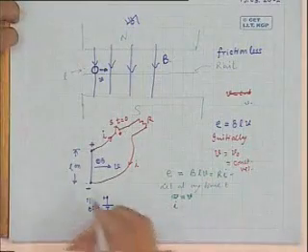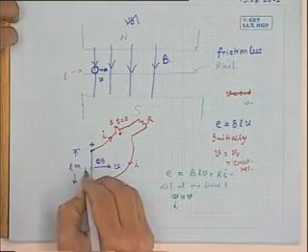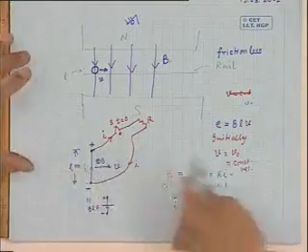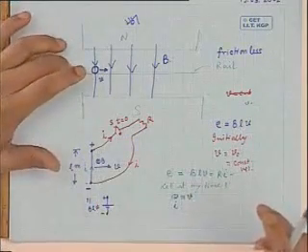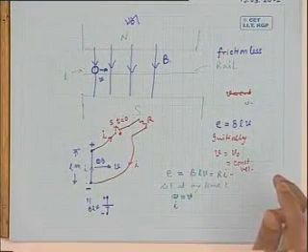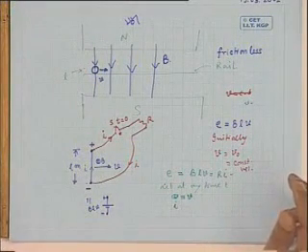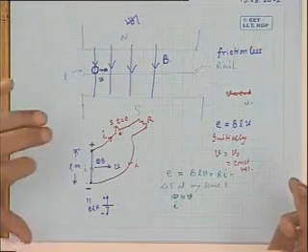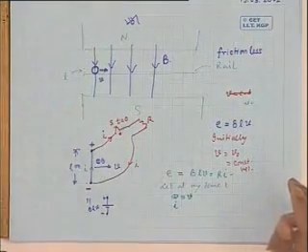Now, you see that when this conductor carries this current I in this direction, it is placed in a magnetic field. Therefore, a current carrying conductor placed in a magnetic field will experience a force. That force was absent when the switch S was opened. But the moment it starts delivering power output to this resistance R, it should experience a force.